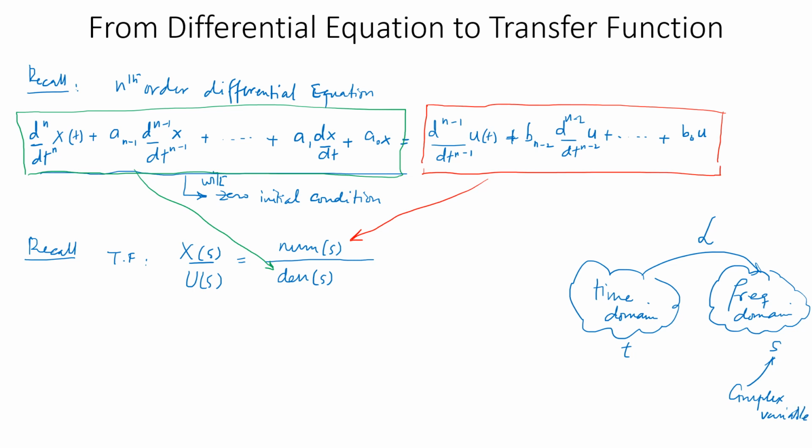Now, with this realization that you have to write down a transfer function in the S domain, you need to take the Laplace transformation of the expression. And since the zero initial conditions are indicated, this is not going to be overly complicated. That would be something like if you have the assumed input to be b e raised to power st, which is the assumed input. That would mean that the solution of X is going to be, because these are linear systems, of the same type. So this is going to have some change in the amplitude, obviously, but the nature of the signal would remain intact because of the linear system.